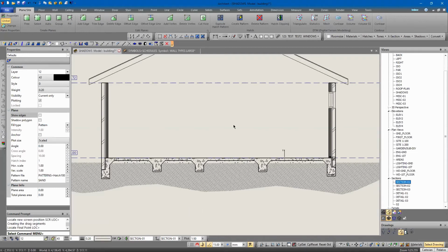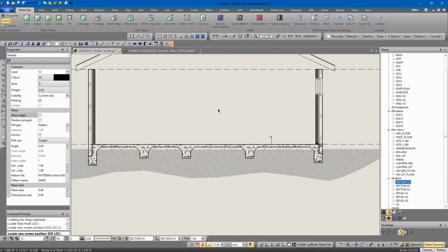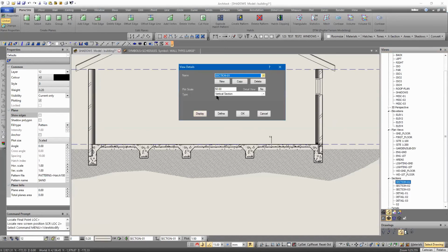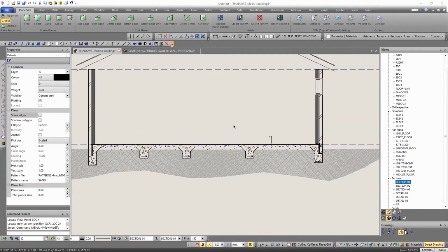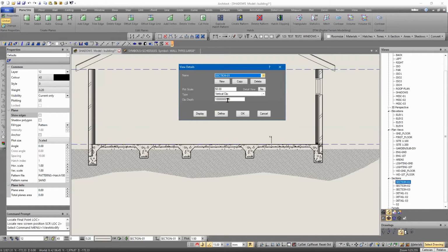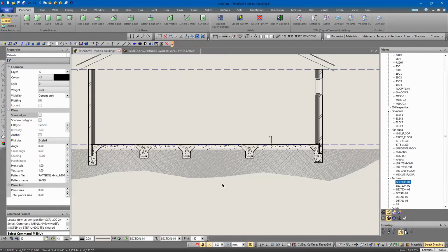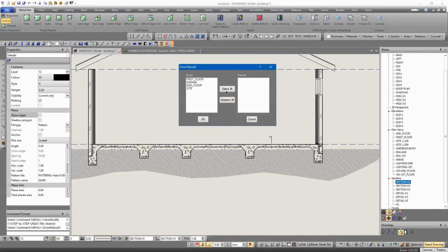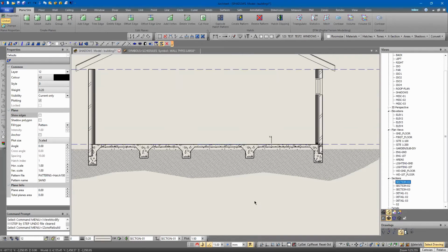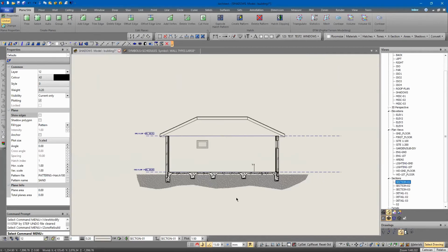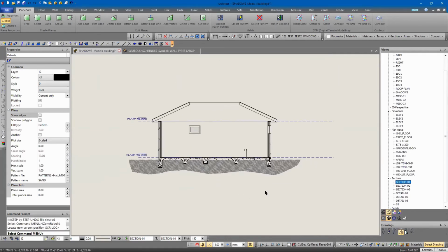This is vertical clip or? No, this is just a vertical section. What's the right name for it? Vertical section. Yeah, clip. Yeah, I usually use vertical clips. So if we go to vertical clip, it goes a long way too far, but anyway, we can do that. And then we can do rebuild. No problem. It's still okay, it still works. Still works perfectly fine because I'm not putting this down past the end of the building. I'm only putting it back 10 mil.